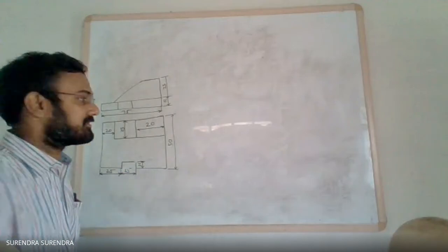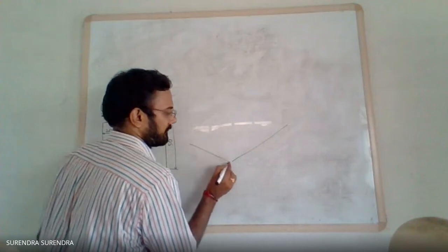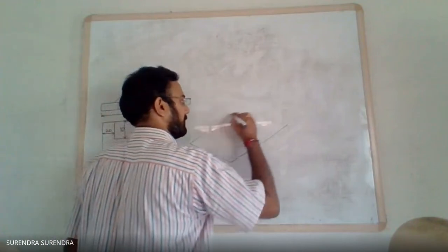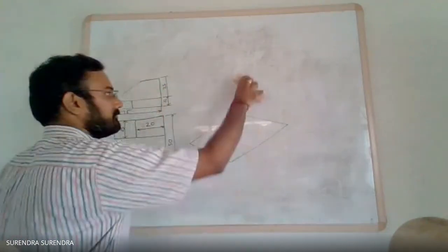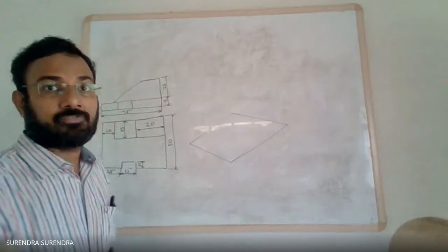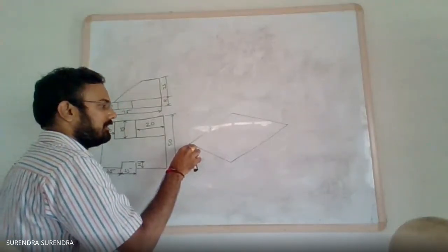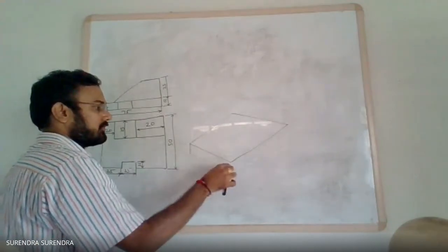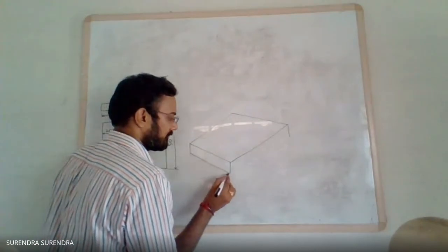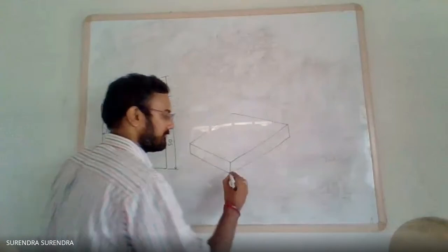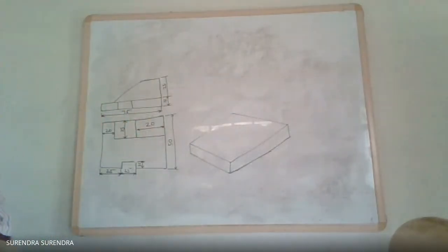First, initially we can consider the rectangle: 75 mm, 50 mm. It is for a height of 12 mm. We can draw upward or downward. Better, to avoid erasing lines again, I am drawing only the visible 12 mm: 12, 12, 12 mm. These are the only visible surfaces.